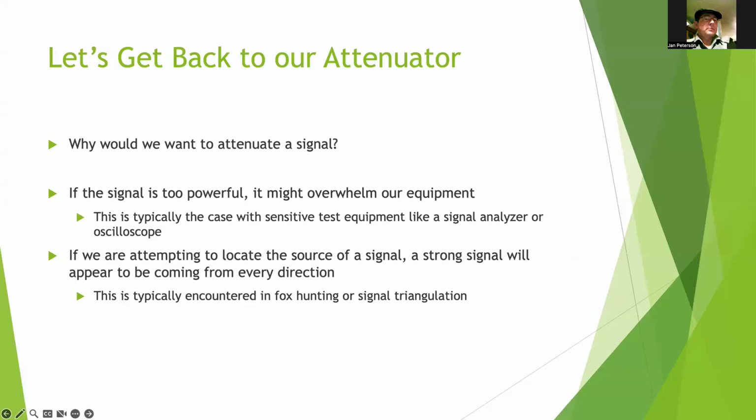They'll turn around until they can hear the sound, and then it should be right in front of them, right? That's not great. But with an attenuator, I can combine an attenuator with my Yagi and still maintain the very directional capability of the antenna, but reduce the signal enough that I can still hear the difference as I move around it. This type of antenna that Stan has right here is a Yagi antenna.